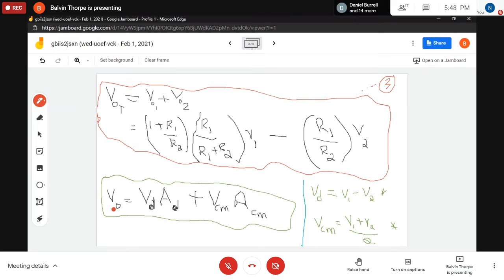But we also know that that same operational amplifier will actually operate in a common mode configuration if both inputs are seeing the same voltage. Even if you're applying the voltages to be different deliberately, there are sometimes voltages that are going to be picked up by the same amplifier that are the same.